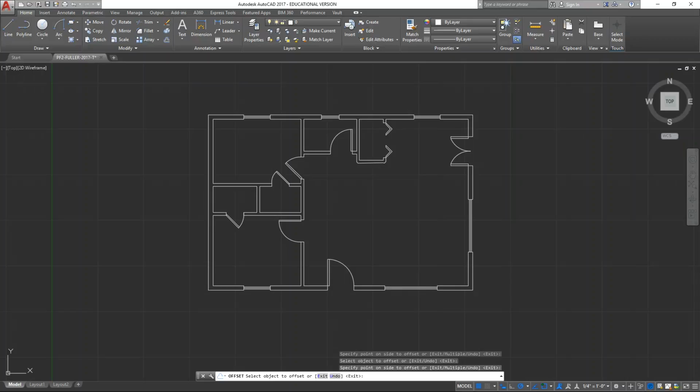One is so we can more easily read our drawings once they are printed up, and we can look at a drawing and say, okay, well, that is the color red, so we know that is an exterior wall. And also, we do use layers in the design process because as we're designing, something may be getting in the way, and we can actually turn our layers on and off as we're designing, and turn it off so we can create a certain piece of geometry and then turn it back on when we're done.